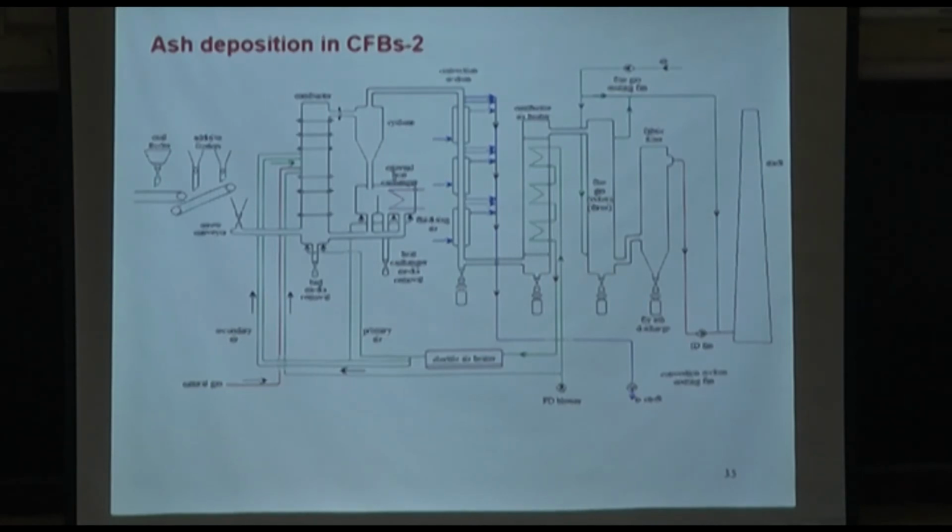at regular intervals. What we haven't shown in here is that we have a bed media removal system, which we used to operate about once in 24 hours. So there was a valve. It's a plate valve actually, not a rotary valve.